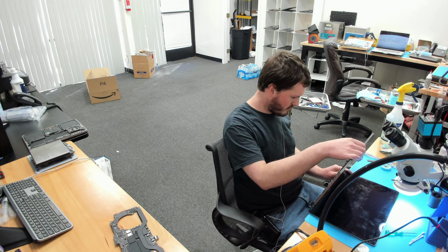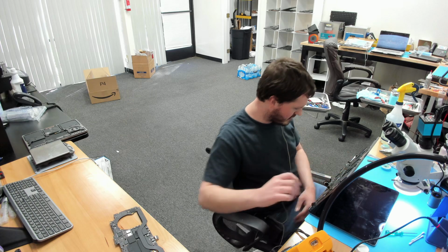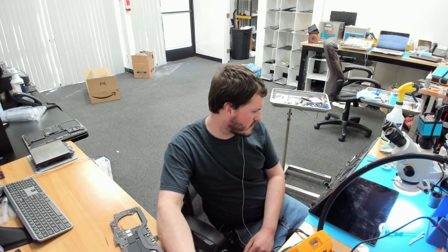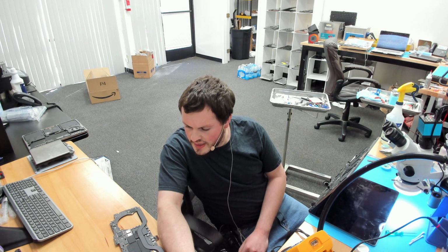0.71. Okay. So it still looks like it's not turning on. Interesting. So we're just going to watch that. That makes me think, so I'm thinking, this got shorted to ground. So we have had a short to ground. If voltage to the NANDs was lower for a second, that could have possibly forced it into DFU or caused firmware corruption. Or it could have damaged a regulator. So it's very rare, but sometimes you can have damaged regulators and damaged resistors from shorts to ground like that.